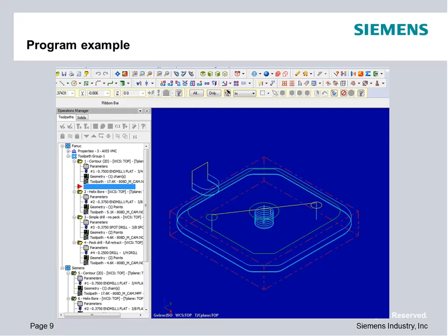When we get to handling the profile of the physical part, we're going to have it posted with cutter comp as a "where" type of function. You'll see that a lot in CAM posted programs. What that means is the actual output cutter path is already compensating for the radius of the tool, but you're still going to see a G41 or G42 command turning cutter comp on, so you can still adjust the resulting cutter path. And there are some challenges when you get to working with systems like that. So we're going to talk about it, show you a few different tricks, and apply that through.